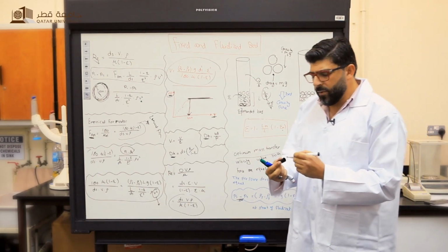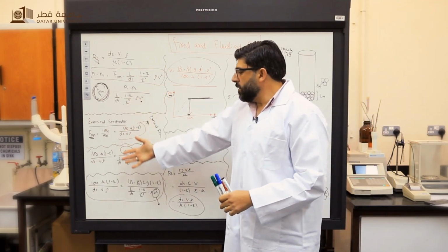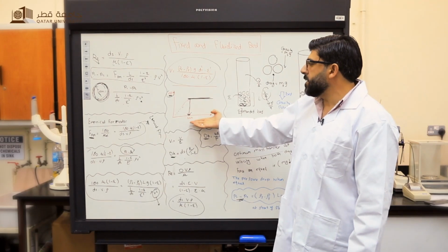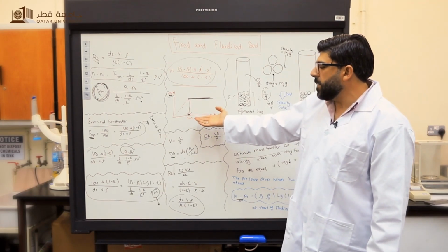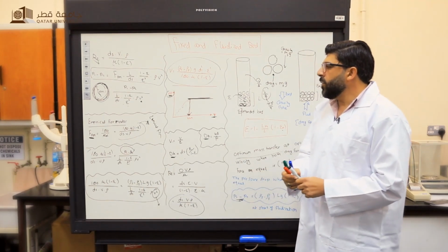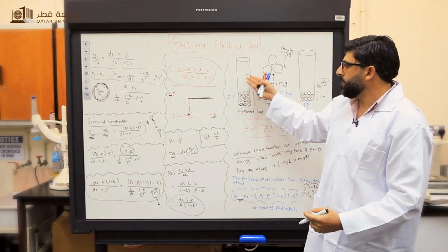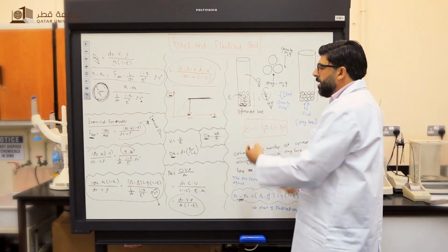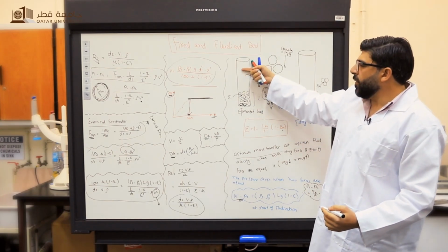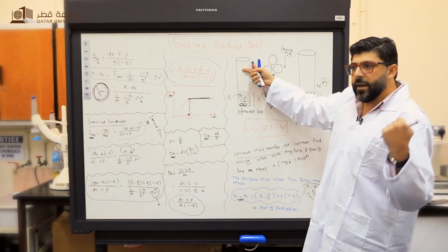So this is all about the fixed and fluidized bed experiment. The empirical formula we used to find the minimum fluidization, and also the experimental way to find it for the fixed and fluidized bed. In the experiment now we will see the pressure drop. We have different types of particles and fluid. For the fluid, we have two types: we have gas and we have liquid.